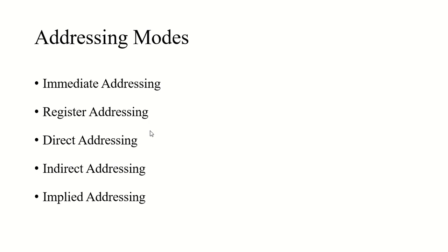right? And operand can be specified in a number of ways, right? It can include an 8-bit or 16-bit internal general purpose register, or a memory location, or any memory address, 8-bit or 16-bit, right? Or even it can be an implicit operand, which means the operand is not specified. Instead, it is assumed in some register. And depending on the number of bytes or bit patterns required to specify operation and data, the instruction set is divided in three types: 1 byte, 2 byte, and 3 byte.